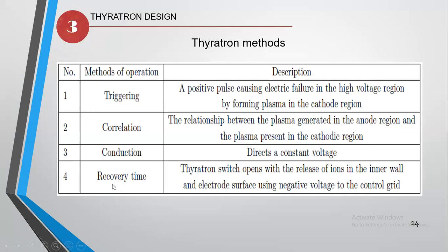We use hydrogen gas because of its short deionization. The recovery time required depends on the gas in the tube, and as told earlier, hydrogen has a short deionization, unlike the other gases.